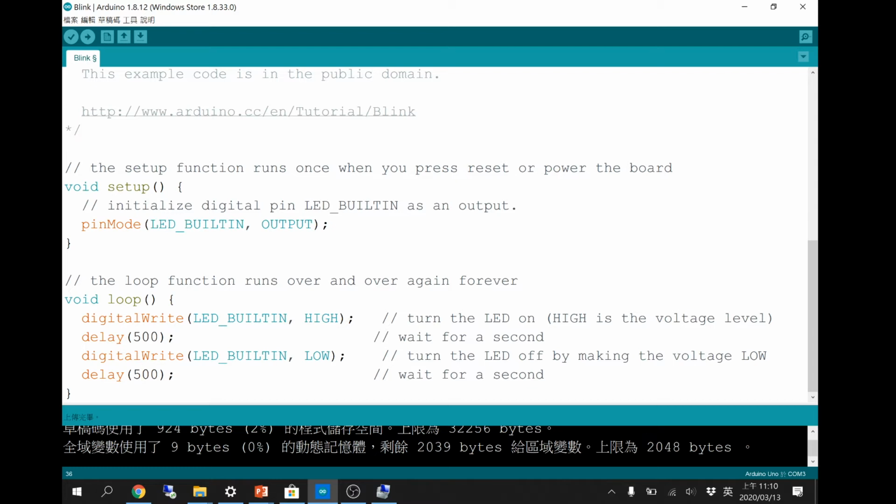But of course, you can find here there's a LED built in on the board next to pin 13. This is the same because this is the built-in LED connected to pin 13. Okay? And next, please help me see how fast you can make the blink. Right now we changed from 1000 to 500, which means we have a 0.5 seconds blink on and blink off.